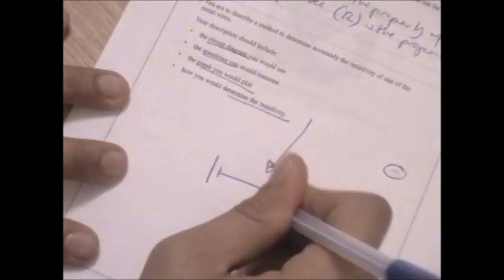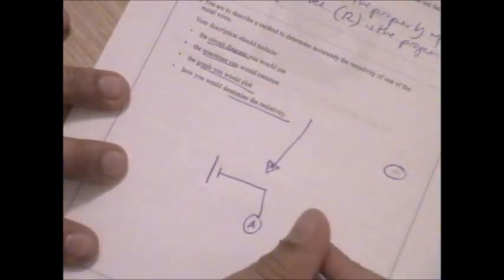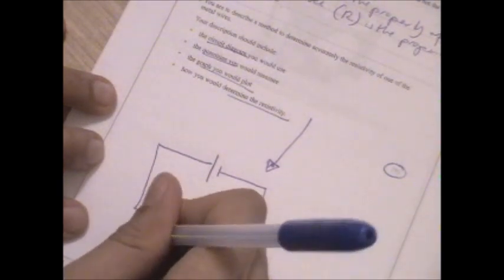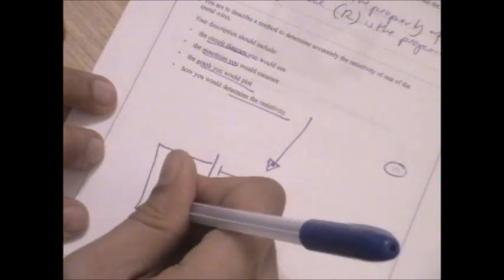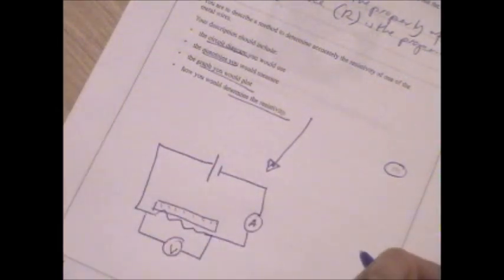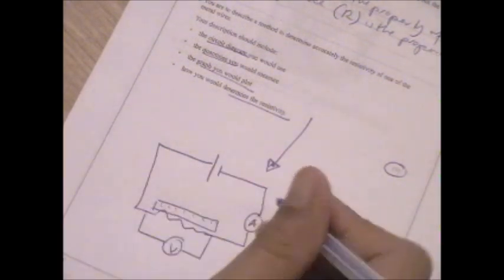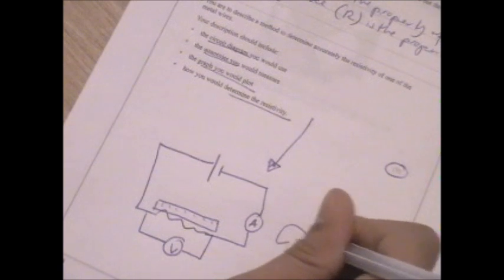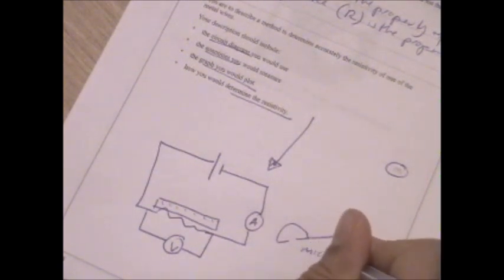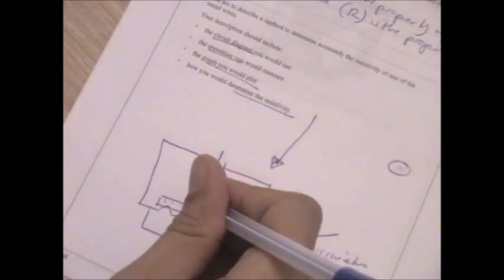So in terms of the circuit diagram, I'd use my space below over here to draw my circuit diagram, or you could do it up here, but in terms of the space that's left, why not use that? Just make it clear by drawing a line down that you are using that space there. So the circuit diagram, obviously you need some sort of power source. Remember to include an ammeter. You've got your test wire that you're putting in there, and you complete the circuit with that. And then you've got your voltmeter in there as well, and you need some form of ruler to measure the length of the wire. Also, you need something to measure the cross-sectional area, and that's where you've got something along the lines of a micrometer to do that. So make sure you label any non-standard circuit symbols like micrometer, like ruler.